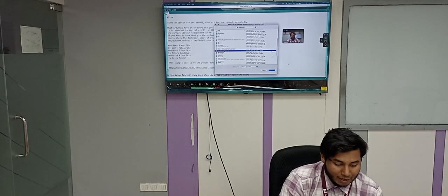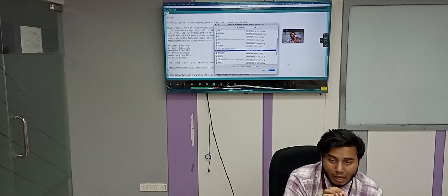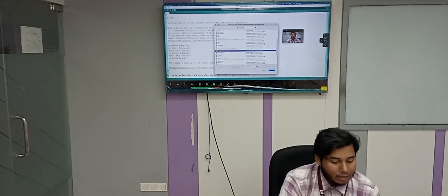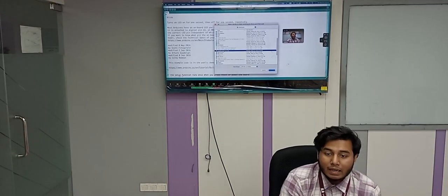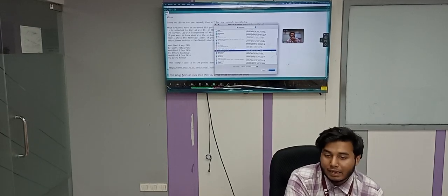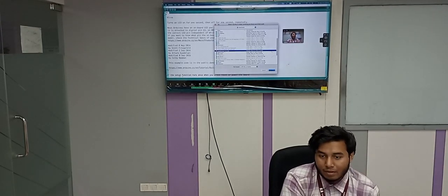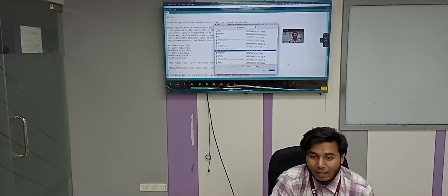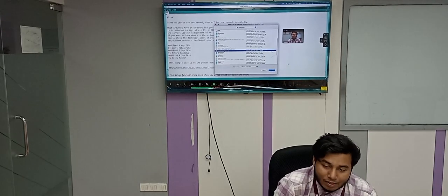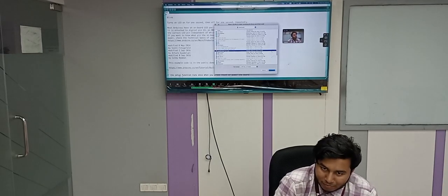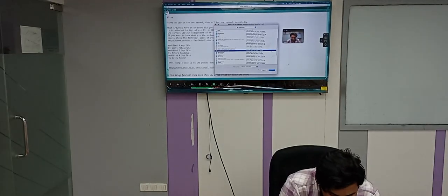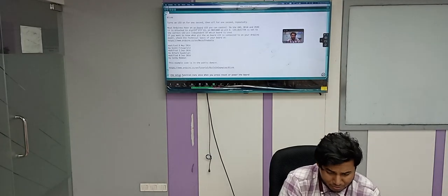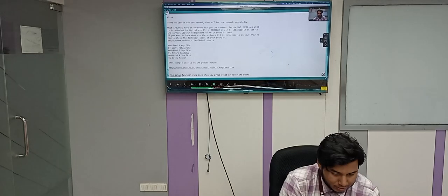Okay, so every time you see you have to declare a .h file. Basically it's a header file. A header file cannot compile with your IDE unless you have added your library. So it will never get access to your Arduino IDE unless you have added your library. Do you get my point? So what I have to do is choose this file. I have already chosen this file, and most probably it has been added.